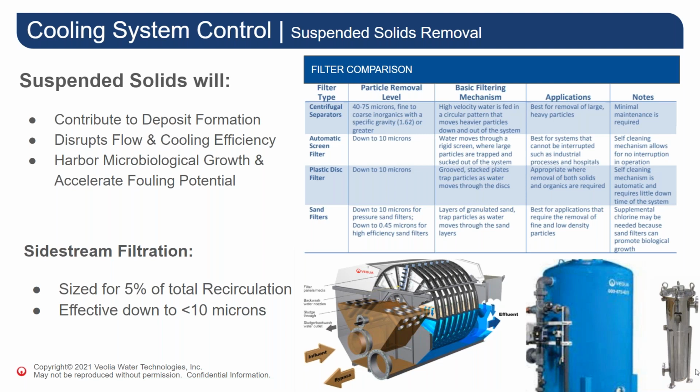Decreasing suspended solids can also help reduce microbiological growth in the system because suspended solids can be a good source of food for microbiological organisms. Again, if you're located next to a farmer's field, you already know that. Every time they fertilize their fields, the tower gets green. Decreasing biological growth, in turn, helps to reduce the biologically influenced corrosion.